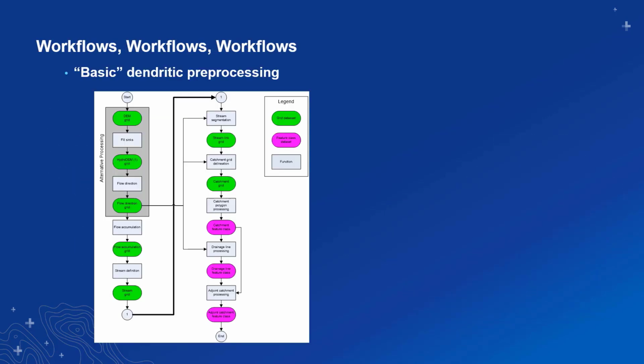This is where terrain hydroconditioning comes in. Hydroconditioning is making the water flow over the digital representation of the terrain in the way you want it to flow. It is about developing a flow direction raster that reflects the correct or expected behavior. There are many workflows that can be used to develop hydroconditioned DEM that are captured in ArcGIS Tools.